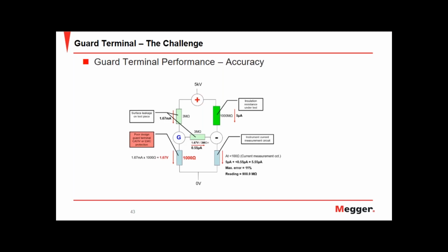So the use of resistors is not a good idea. However, many competitors revert to this method. Mega doesn't do this. Mega has very fast changing circuits that could detect a transient and block it. And when the transient has decayed, that blocking is then lifted. Now the advantage of that is there's no impact on the accuracy of the instrument. We don't worsen the accuracy of the instrument by putting resistors in there. We keep the impedance of our circuit low when we measure, and then we increase the impedance of our circuit when a transient is detected.